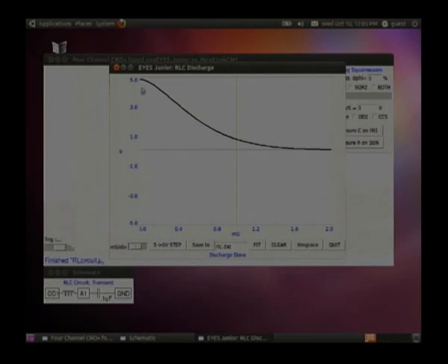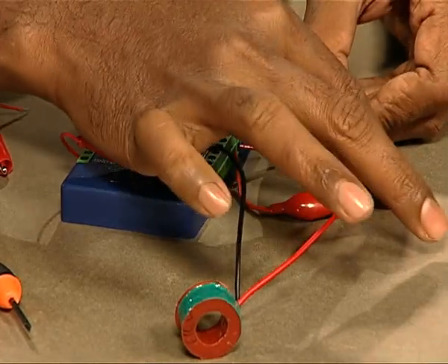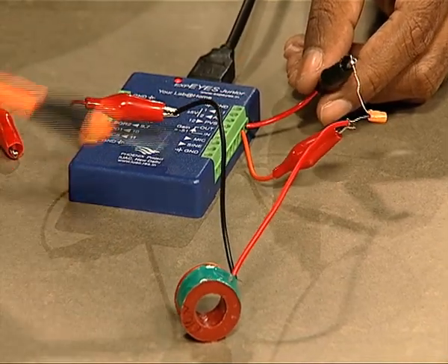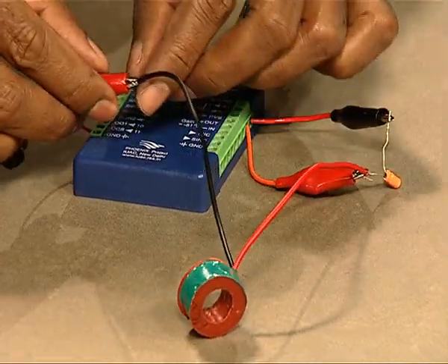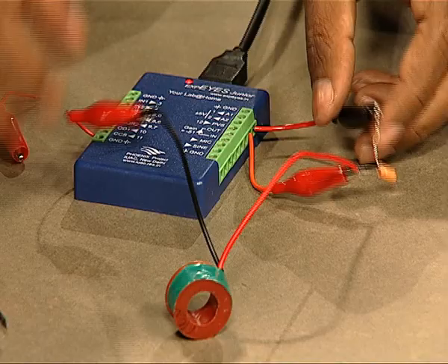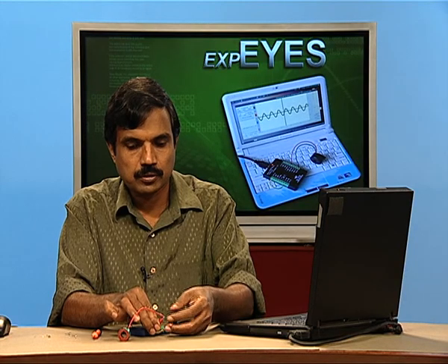Let us go to the screen and do the measurement again. We can see that this also does not oscillate; from the look of it, it is either overdamped or critically damped. So, that means the nature of this voltage depends on the ratio of the capacitance to inductance, that is the C by L value, and also the resistance in the circuit. It is possible to do the experiment using a wide range of capacitor and inductor values and verify the measured resonant frequency with the theoretical value.